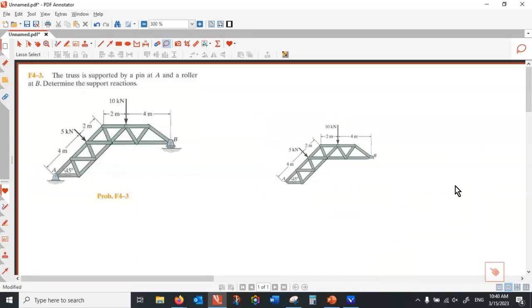Okay, so B, what type of support is that? Am I releasing that from B or am I releasing that from the roller? I have two options. I can release it with the roller or I can release it without the roller. If I release it without the roller, that would be point B, that would develop two reaction forces. And then that's a problem. Why? Because at A, this is a pin support. I have two reactions over here, two reactions over here. Difficult to solve, isn't it?